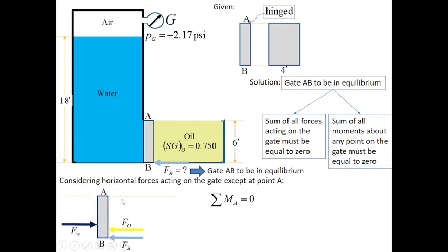Now, we consider this part wherein the gate is hinged. And from that part, we consider this vertical distance from point A to the hydrostatic force due to oil. Because when you take moment, we also consider the distances, the distances that are perpendicular to the forces. Okay?